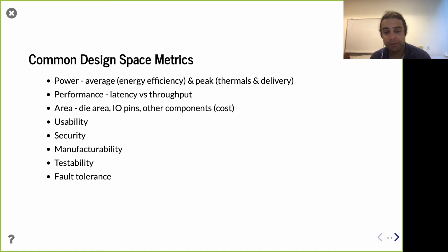For this class in the Chisel FIRRTL world, the standard practice is to turn it into Verilog and pass it off to an existing tool flow. One of my pipe dreams as an instructor is for someone to build a lightweight FIRRTL pass that can take the FIRRTL for a design and make an analytic model. It wouldn't be perfect, just a model to give you an approximate area and power consumption. There's reason to believe this is possible. Intel had something like this as a research prototype, 4 years ago, more than that. It's bit rotten with the newest version of Chisel, so we can't use it for this course, but something like that would be great.